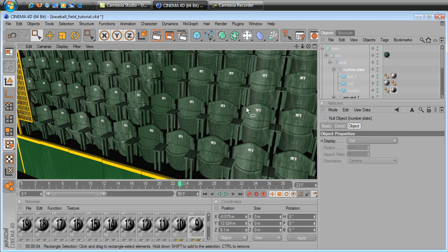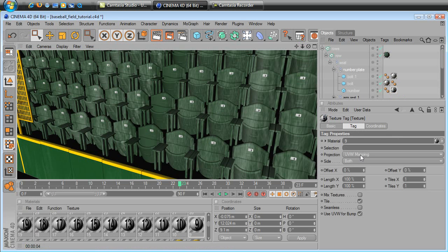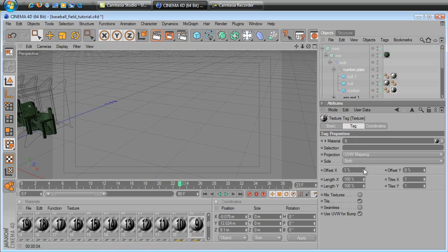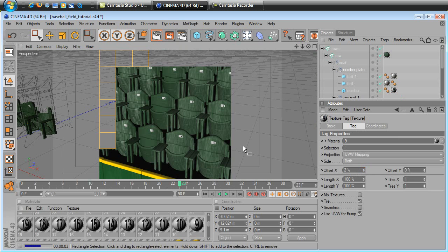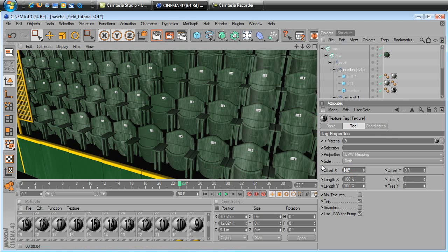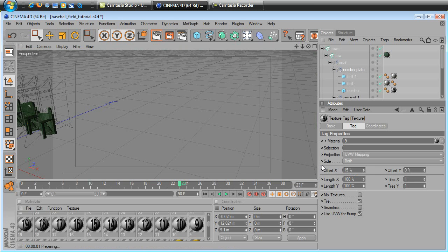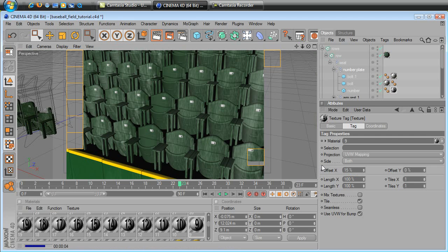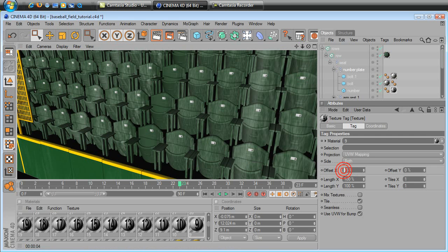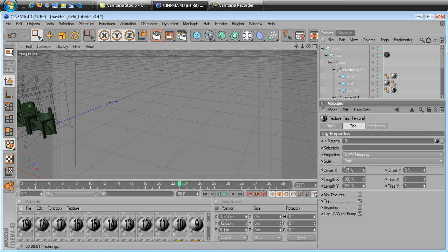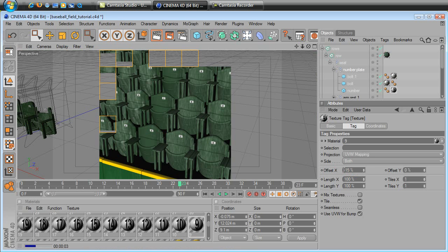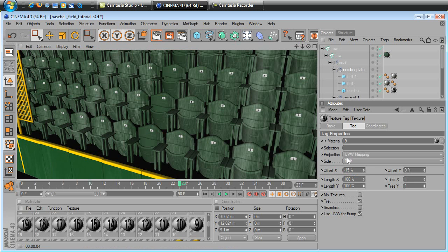And it looks like it needs to be offset just slightly in the X dimension, because it's just not perfectly centered when we apply it to our material. Let's see if that did it, just like a 2%, maybe more, 15. Oops, going the wrong way. Do negative 15. As you can see, yep, there you go. Now it's centered. So you might have to fudge that around a little bit, but that's good.